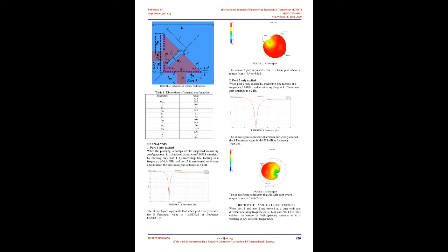2 Design and Analysis. 2.1 Design. The proposed specification is prototyped using the copper laminated RT/Duroid 5880 substrate, 1.57 mm thick, dielectric constant 2.2 and loss tangent 0.0009. In this proposed design, the HMSIW resonator operating in dominant mode is split into 2 unequal parts by etching a one open-ended slanted rectangular slot. This slot transforms the HMSIW into 2 unequal quarter mode cavity resonators.